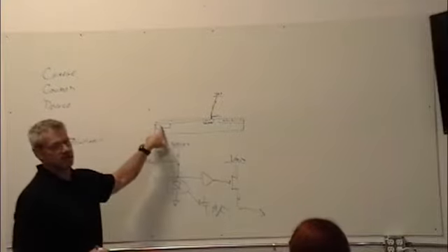So C is really, really small. It's down to minus 15. That means when I divide by it, it shoots way up. So even though I'm only putting maybe 50 electrons on there, and total charge isn't very much, I'm effectively amplifying it by the capacitance that's on it.